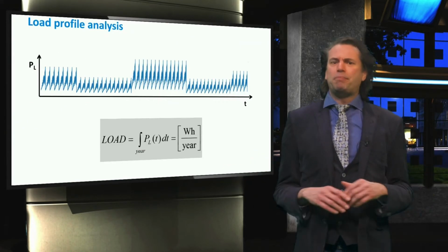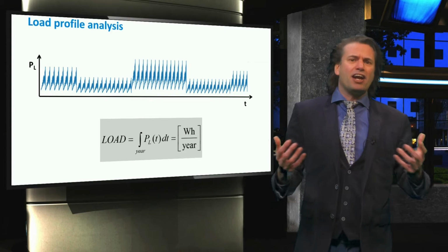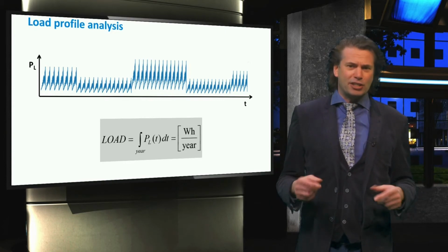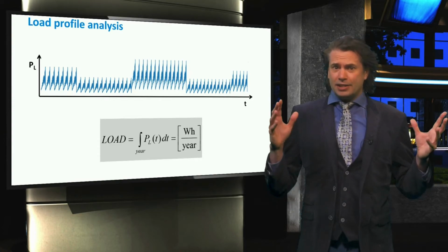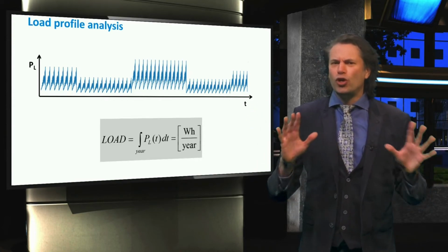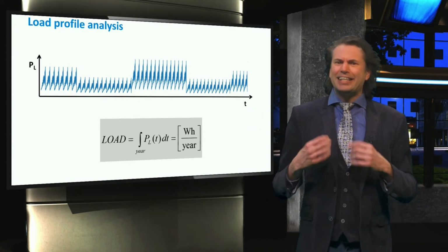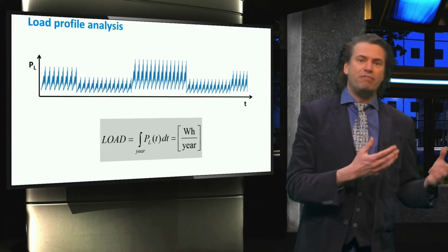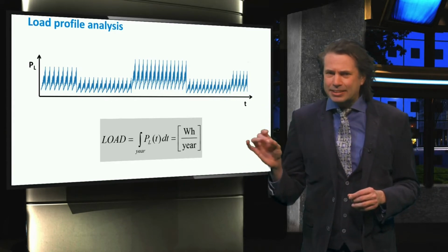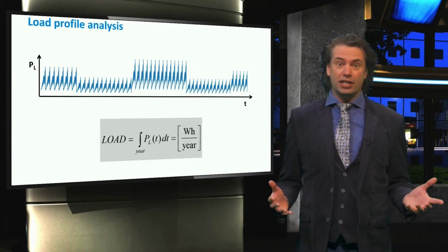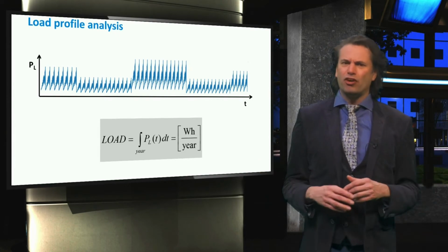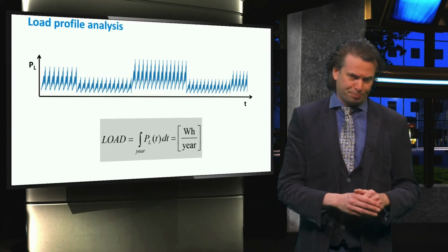In any type of PV system design, an analysis of the different load demands is one of the first steps that needs to be carried out. The advantage of carrying out a good load analysis is that it leads to an optimum PV system design by estimating the correct number of PV modules. In this way, an accurate sizing of the PV system can be achieved.